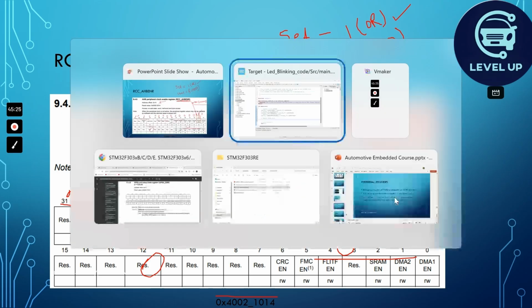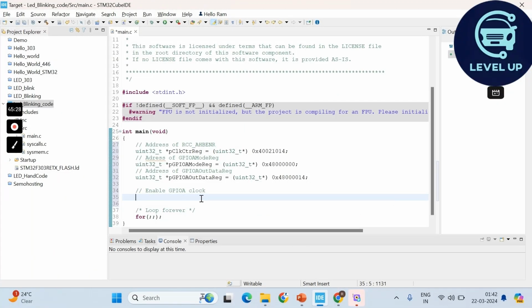So we will do the same like that. What we need to do is just dereference it. By dereferencing, this is the dereference of that particular memory location, then we OR it with what? 0x, what is the mask? 0x00020000. Okay, so this represents that 17th pin is set.